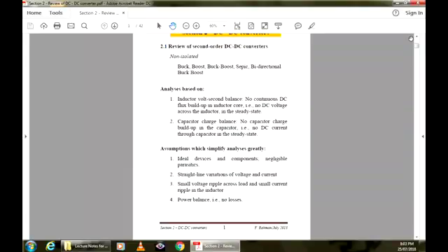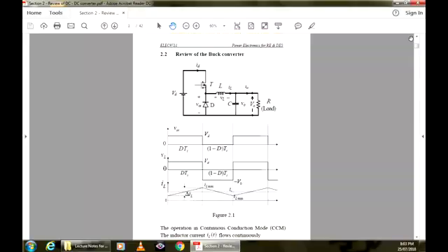and then find the characteristic of this converter. So this is the buck converter which we first deal with. The buck means the output voltage is lower than the input voltage. This is an American terminology. Another term for it is step-down converter. That means we are producing an output voltage which is lower than the input, and that's what a buck converter does.